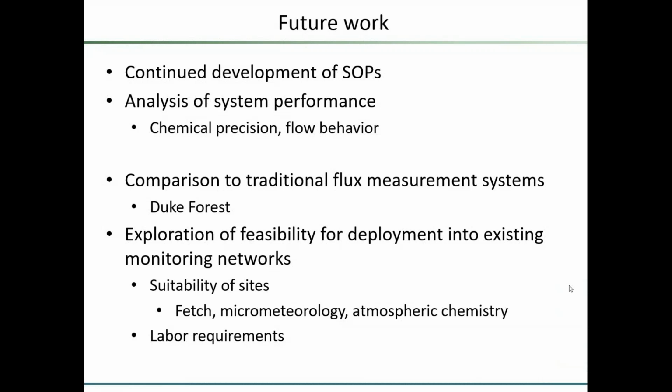A question for you about your instrument. How quickly can you, or do you need to be able to switch from one mode to another? And then based upon that, what is the residence time, and does it matter from the inlet to the filter? I'm wondering, if you start to switch relatively quickly, could you be leaving mass in your inlet that never gets to your filter, or gets to the filter at the wrong time, which could be uncertainty in the analysis?